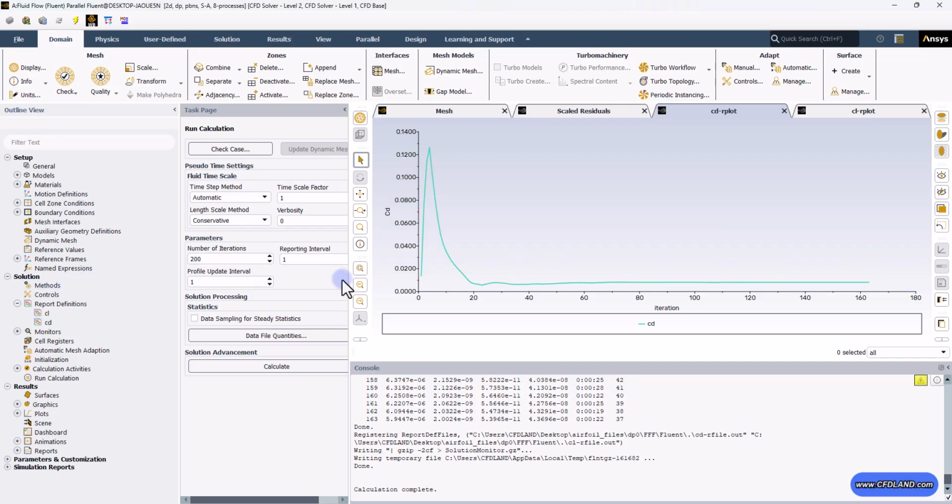So I want to start post-processing by measuring the drag and lift coefficient to compare to Ladson experimental data. The post-processing stage is where we act as engineers and deliver a verdict on the simulation's accuracy. So we want to start by comparing our computed results to the experimental data from the NASA wind tunnel test.